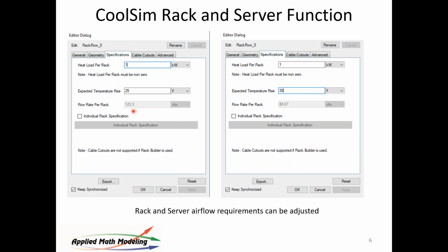Over here, I'm 123. So you can take any data center, and this is again a CFM number, take the amount of heat load you're trying to dissipate in the room, multiply it times 100 to come up with the flow rate you need to make that data center cool. Now, it says nothing about the ability to get the cool air to those servers. That's a CFD issue, distribution of air. But what it does do is give you a fairly good feel for understanding how much cooling capacity you need.